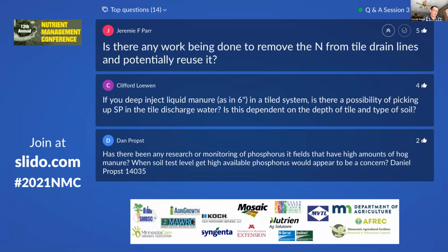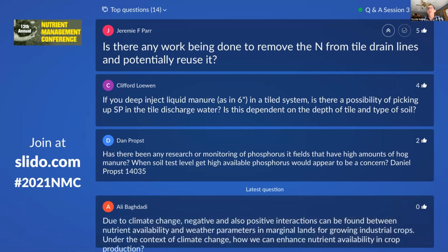Yeah, Fabian, I was going to mention Jeff too, in his presentation last week. I think he did a nice job with this. I thought of two ways you could think about this. Controlled drainage is a way people are doing this, by holding back water during the growing season and having the crop actively use that. And then there are also some people down in Arkansas who collect all their drainage water and reuse that.